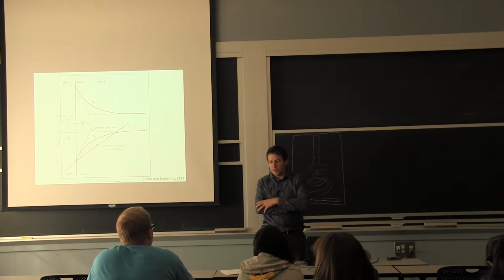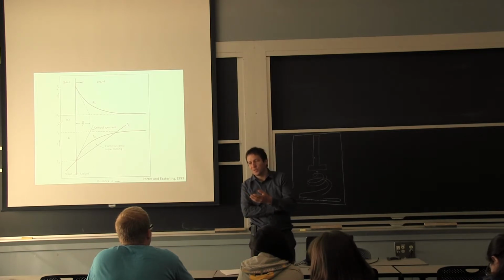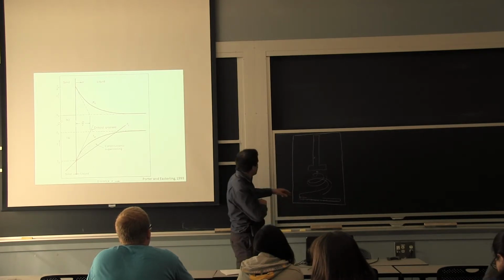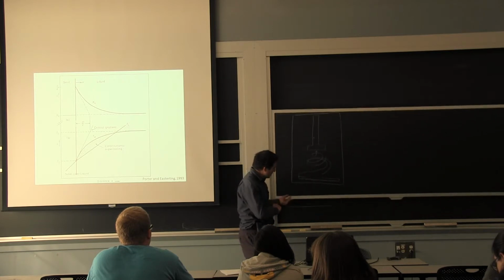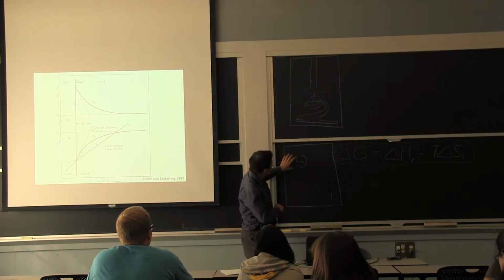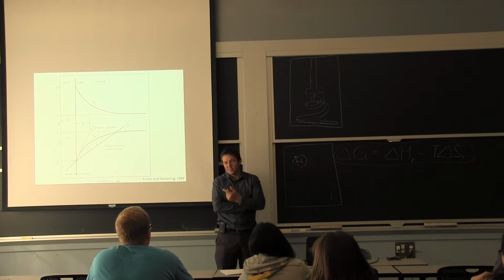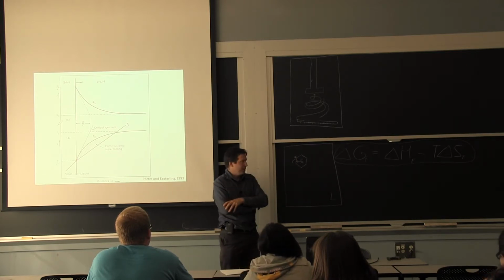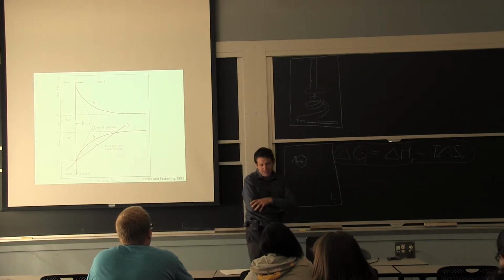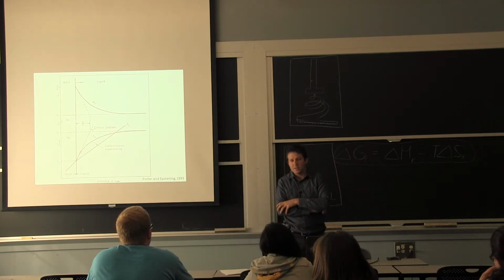It's very common to have some supercooling when we go through solidification, but not the 200 or 300 degrees that we talked about if we had to do it with our single crystal here. That would be 200-300. If you go really slow and you're doing silicon, maybe a degree. A typical case is, say, 10 degrees or so.